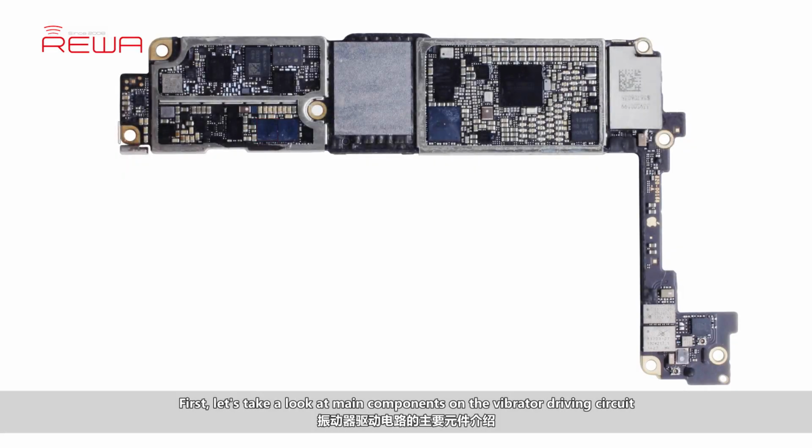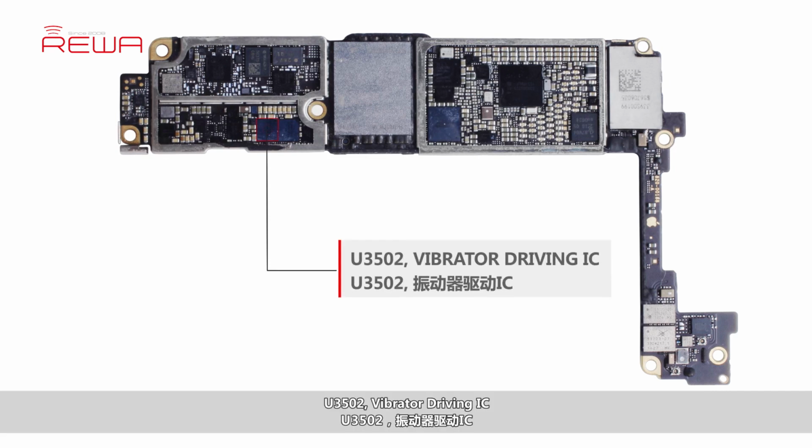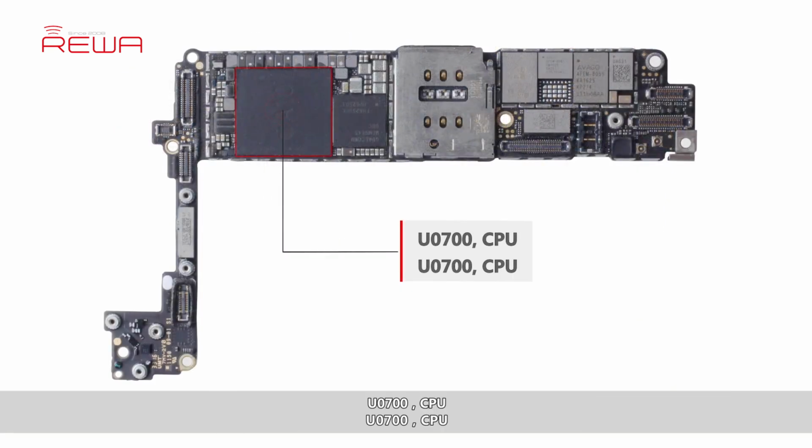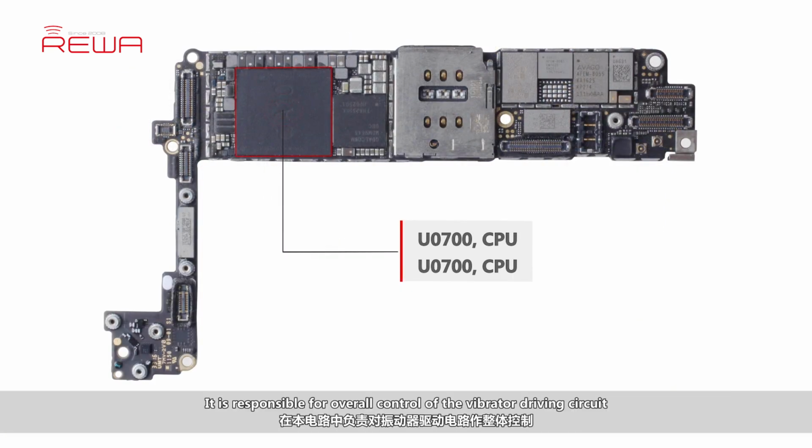First, let's take a look at main components on the vibrator driving circuit. U3502, Vibrator Driving IC. The driving voltage from U3502 drives the vibrator to work. U0700, CPU. It is responsible for overall control of the vibrator driving circuit. It also transfers data with U3502.